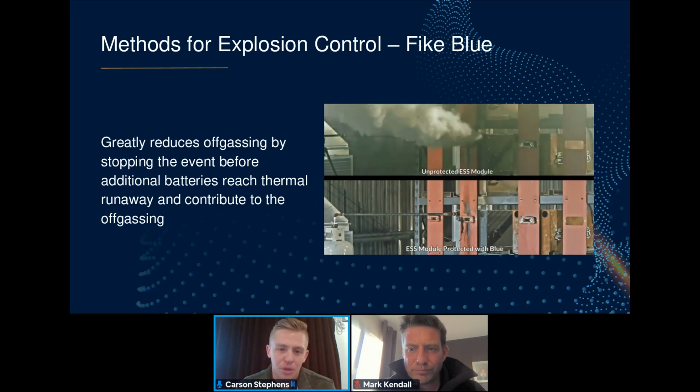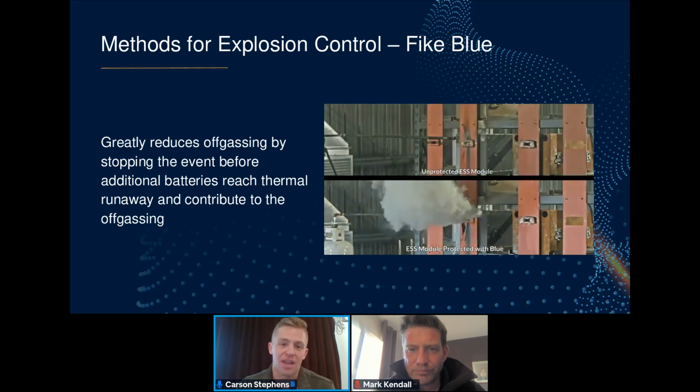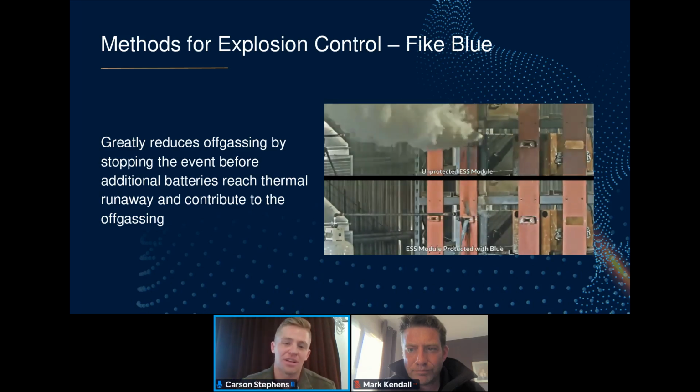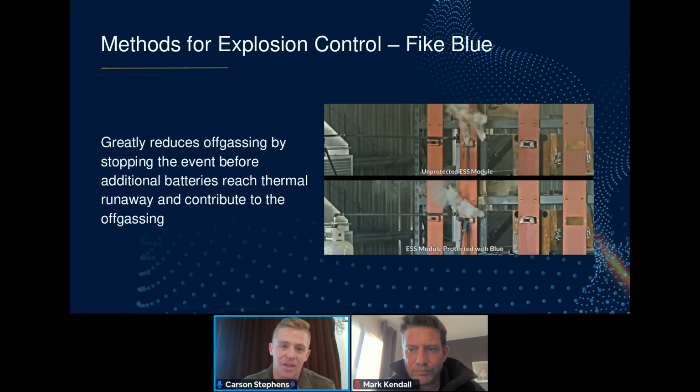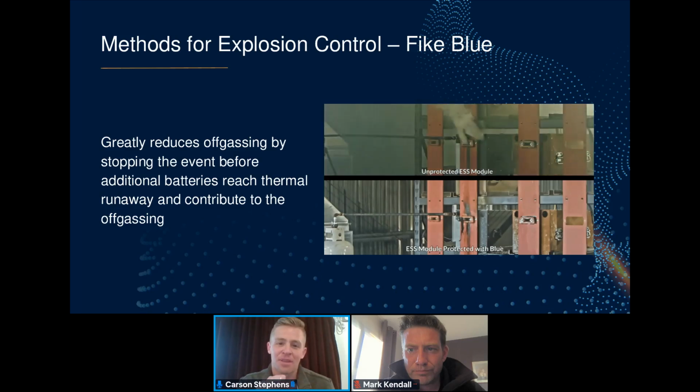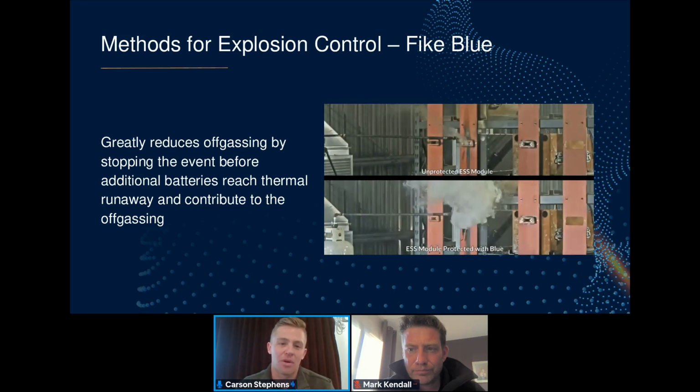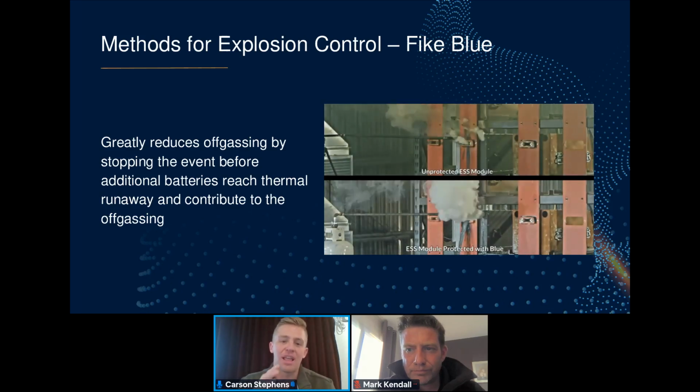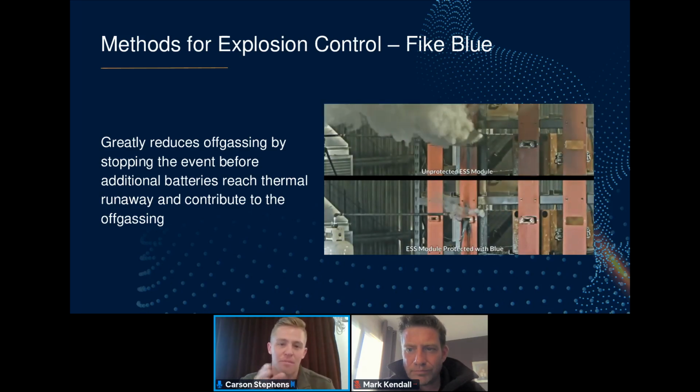So each plume of smoke is another cell that's being destroyed by that thermal runaway event. If you can scale this in your head, each one of these cells, you can see it blowing off more and more. Each one of them is going into thermal runaway. If this whole module goes off, then it's going to obviously move from module to module.